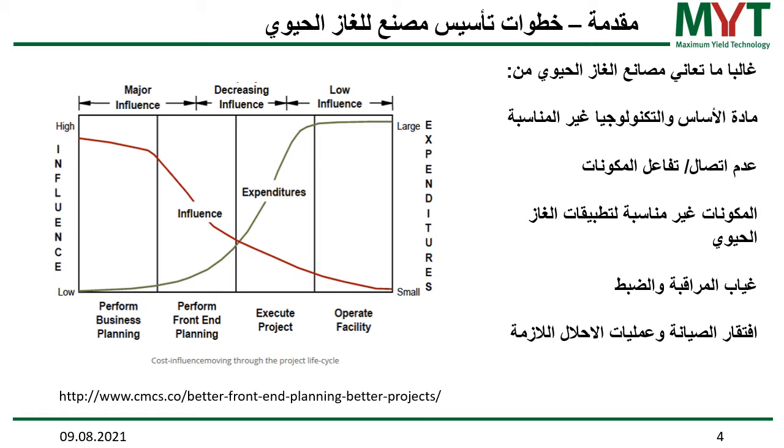You've learned a lot of technology options, a lot of components which you can choose for a biogas plant, and it's very easy to select a pump or a digestion system which fits liquid substrates, but not solids, for instance, or which fits substrates which contain no inerts such as stones, or which doesn't fit stones and inerts, things like that.